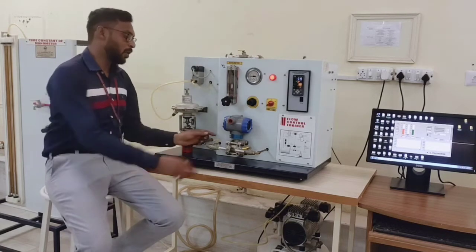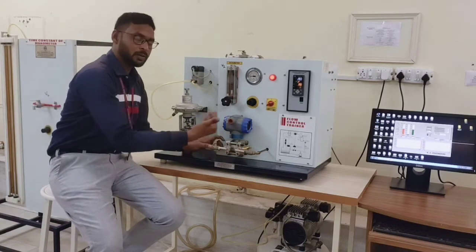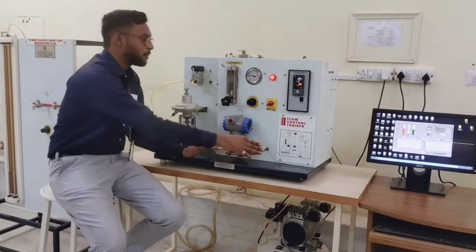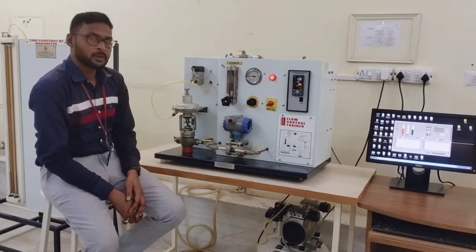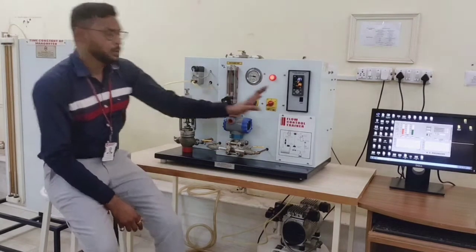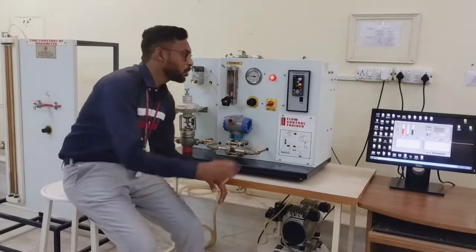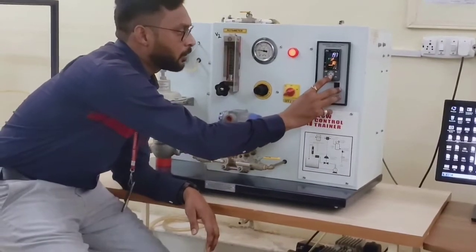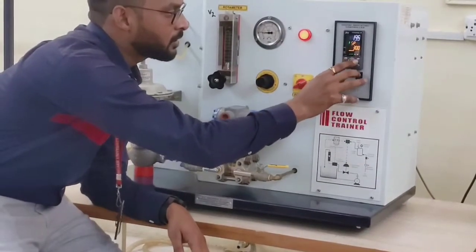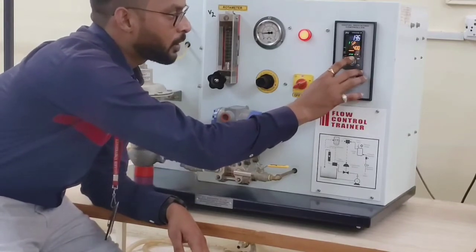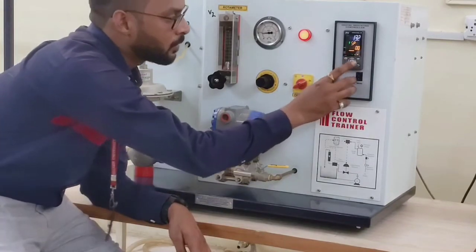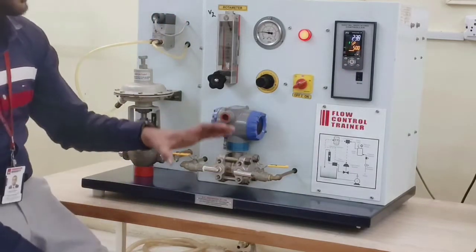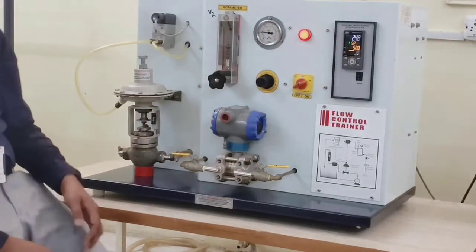Done. And then valve 4 and valve 5, which are like an inlet and outlet of the water. So I am just opening these 2 valves. Both of the valves are completely open. Okay, so now you have a control panel here. You can set the set point at a required value. So what I am doing, I am increasing the set point to 50 and clicking on set. So the set point was fixed at 50. Now we are observing the fluctuations here.